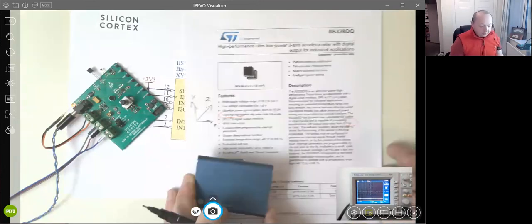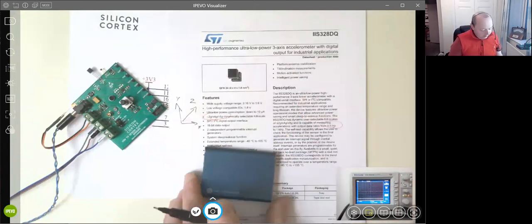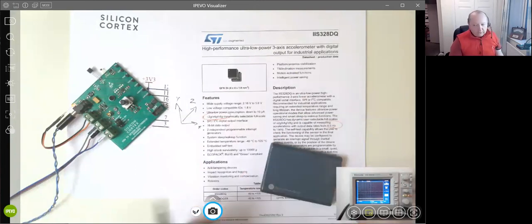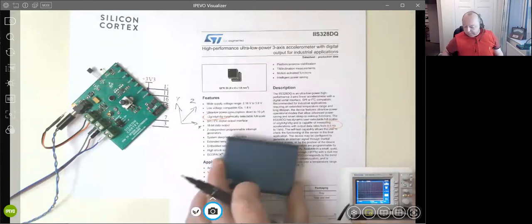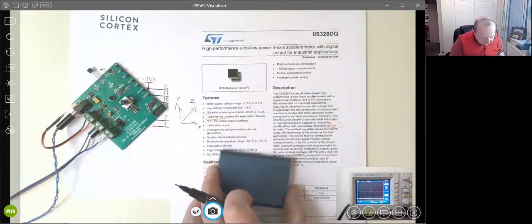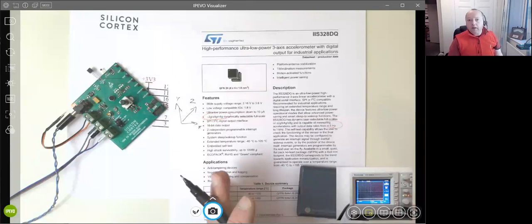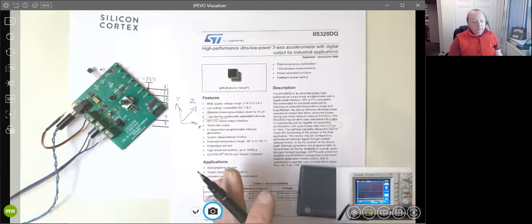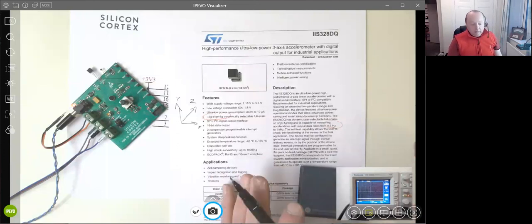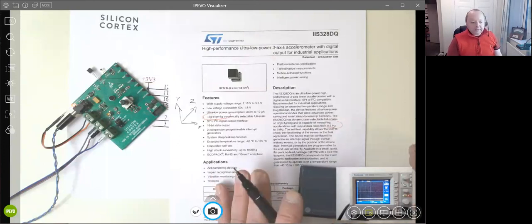We will come back to accelerometers when we talk about I squared C in a future edition, if you like. But they're used absolutely everywhere, these devices. There's probably a procurement problem at the moment with getting hold of them. But with accelerometers, when you start going below 0.5 hertz, they start not working. So the holy grail of accelerometers is really low frequency, but the problem is that they stop responding at really low frequency.